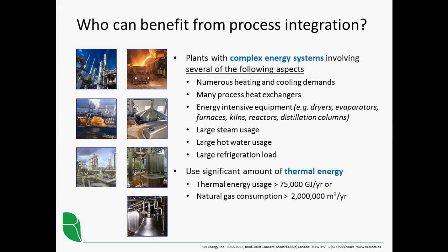Who can benefit from this process integration approach? Well, there are kind of two prerequisites. First, it has to be a plant with a certain level of complexity. If the plant is very simple, then standard conventional techniques will typically be sufficient to determine what energy savings are possible. By complex, I mean plants that tend to be characterized by several of the following aspects: numerous heating and cooling demands, many process heat exchangers, the inclusion of energy-intensive equipment such as dryers, evaporators, furnaces, kilns, reactors, or distillation columns, a heavy steam usage or hot water